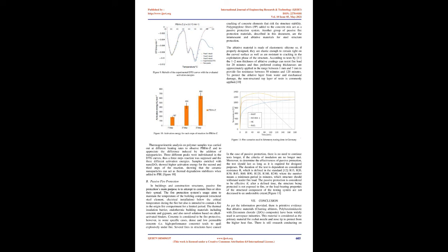Both the standard PICA, phenolic impregnated carbon ablators, and densified PICA offer great weight savings over conventional TPS ablators such as Avcoat 5026, SLA-561, and FRPAs, silica or carbon/phenolic composites. However, due to the limitations of the arc jet facility used, it was not possible to test PICA at higher stagnation pressures. At a heat flux over 2050 W/cm2, PICA exhibited a surface recession primarily due to the sublimation of carbon-based constituents. B. Polybenzimidazole.